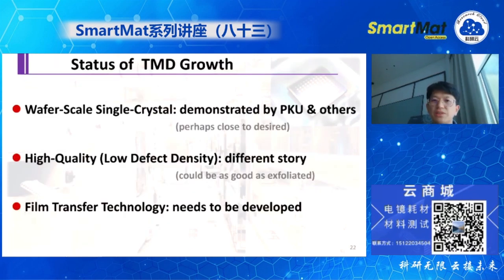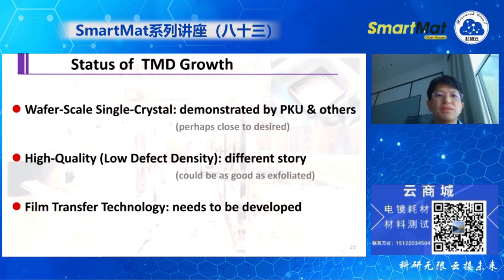Okay, yeah. So let me summarize the status of the TMD growth. So MoS2, for example. Wafer scale single crystal is probably very close to the desire of industry. This has been demonstrated by Peking University, and also probably another few groups. Actually, they will have very nice results published very soon. They all demonstrate wafer scale growth of MoS2 on wafer. So this is probably not a big issue anymore. Single crystal wafer size MoS2 will be readily available very soon.